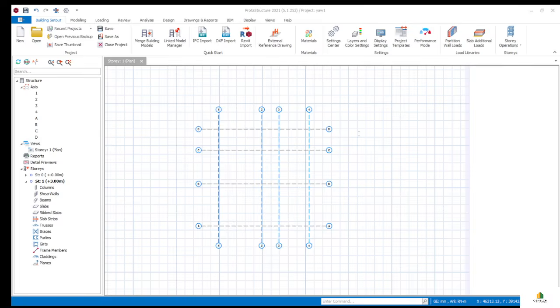How you get it? So total number of stories zero, right? So it said to add stories to the top of the building, enter a number greater than the current total. To insert an intermediate story, enter a number less than current total, right? So we have to insert a number which is greater than the total, the number of stories that we already have.